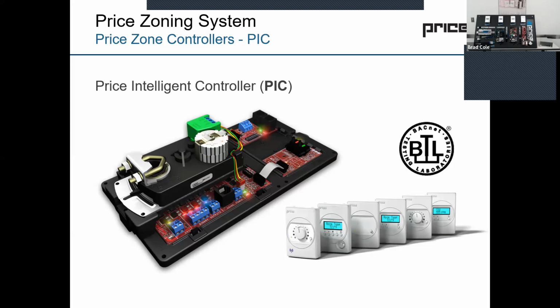It is a BTL certified controller, meaning it's BACnet Testing Laboratories certified, meaning that we can play with other BACnet devices on a BACnet network that are also BTL certified. So this allows us to talk with and tie into all those other guys, whether it's Johnson, Honeywell, Siemens, Alerton, Automated Logic, Schneider. If you're BTL certified, you can talk on the same network and segment and work together. If anyone tells you that BACnet devices cannot talk to each other, they're lying and they don't know what they're talking about. BACnet devices that are BTL certified are like devices.